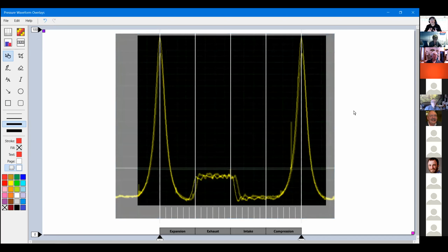I hope you guys can see what I've done. And I tried to explain to you, if the only thing that you take out of this class is how to do what I've just done, I don't really care about all those measurements. What you should very easily be able to discern is that my exhaust valve opening is happening differently on one bank. I've got one exhaust happening significantly before the other side. I've got an intake that happens differently. There is no question in my mind that one camshaft in this engine is operating at a different piston position than the other side. And guys, I don't even have to be a genius at this.